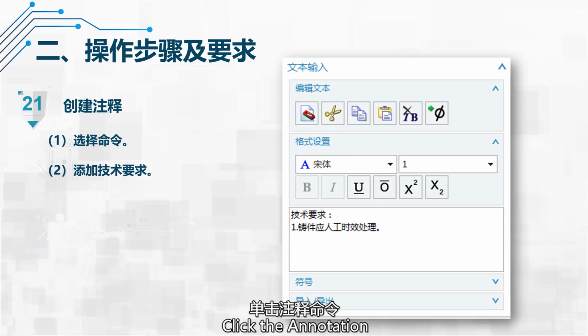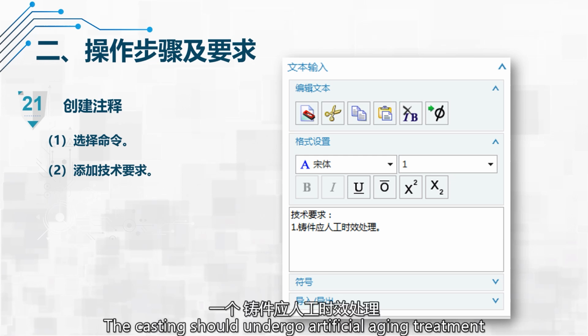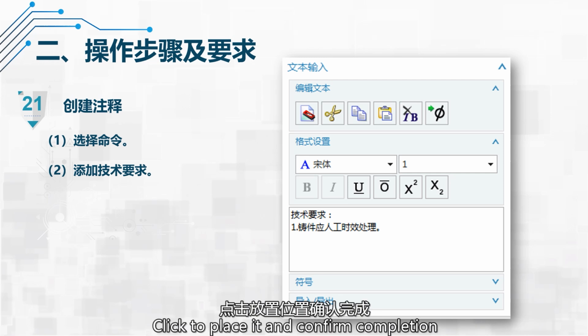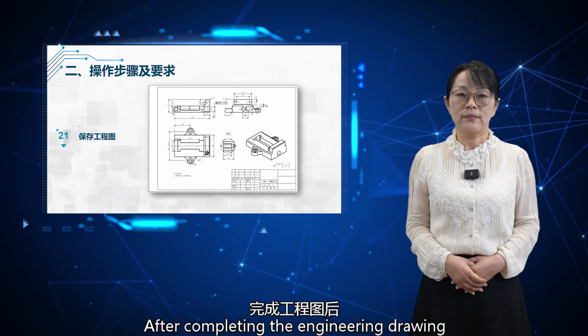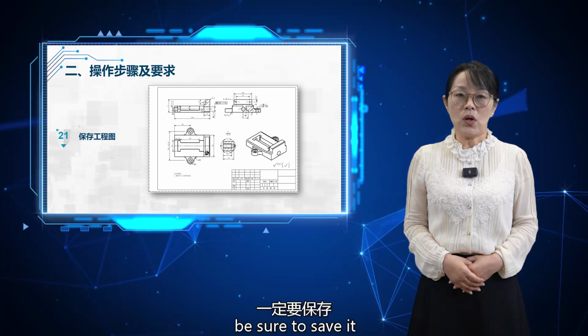Create annotations. Click the Annotation command to add technical requirements. Here we write, the casting should undergo artificial aging treatment. Click to place it and confirm completion. After completing the engineering drawing, be sure to save it.